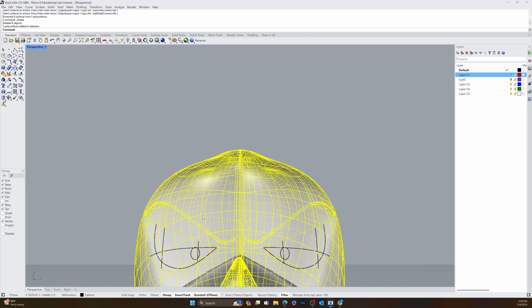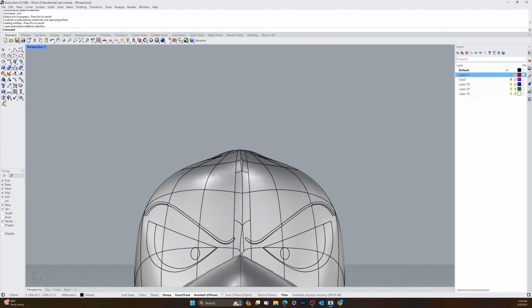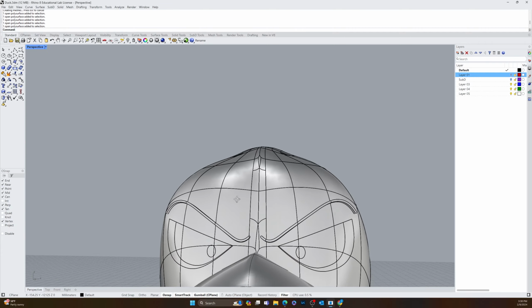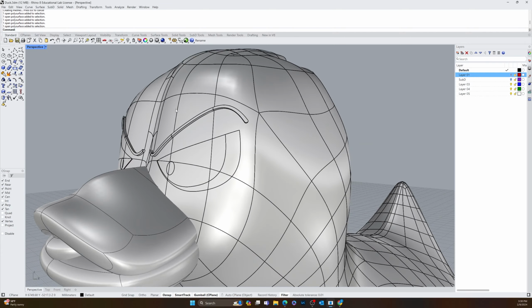So we've done Boolean unioning plenty. That's where you have two objects like two spheres overlapping each other and you make them one piece, just like the picture looks like. But joining is actually edge to edge, and that's why those two puzzle pieces that fit together are going together. So since we made this a watertight solid, we can join it and those edge-to-edge unions will make this all one piece. And that's what we want, if that's working the way you've got all of the edges off the right way.